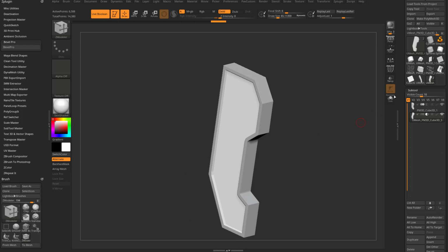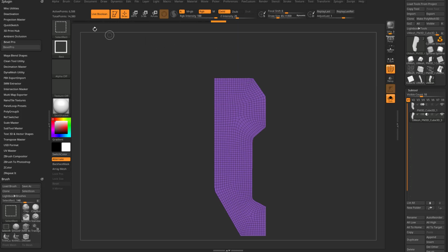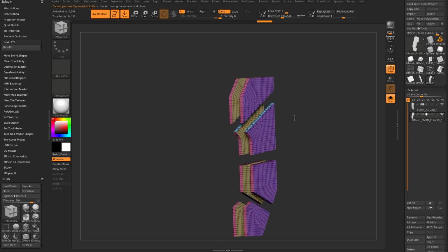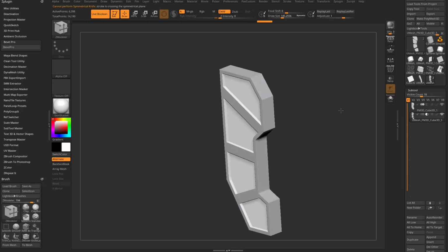And really, just to finish this up, here's what I actually did this for, was for lightweighting. So Control Shift, grab the knife curve, Control Shift, hold down the spacebar, do brush radius, make your brush size so that when you go through and then hold down Alt, you can go through and cut. And actually, we'll go to the corners here, and then maybe one across here. So again, Control Shift, drag, and then hold down Alt before you let go. That'll cut in pieces.